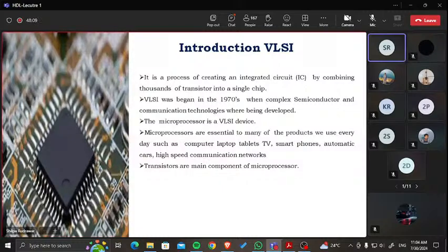Now, why is CMOS preferred? Because you know BJT. What is BJT? It's a current control device. You give some base current, then there is collector current, then emitter current, and that's why it is a current control device. But this MOSFET is a voltage control device. Small gate voltage controls the drain current. Are you able to recall the concept? In that you are giving IB, base current, but here you are giving some VG.